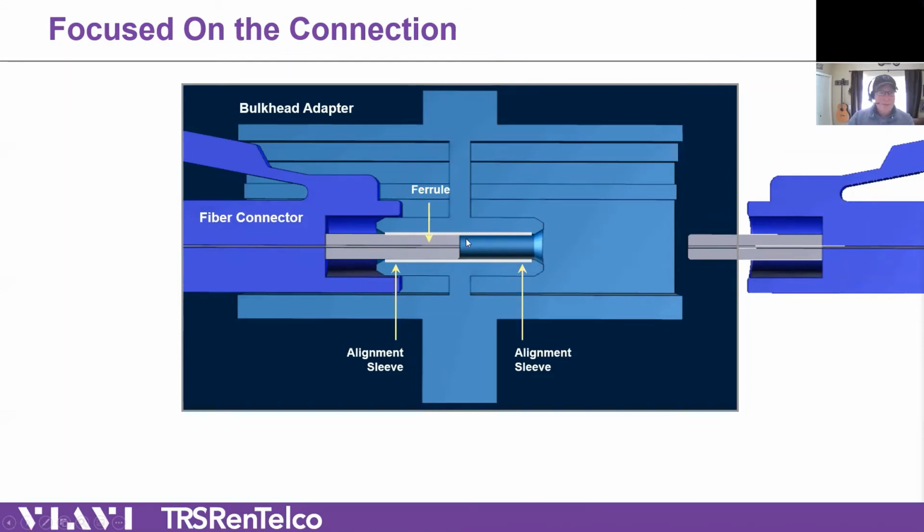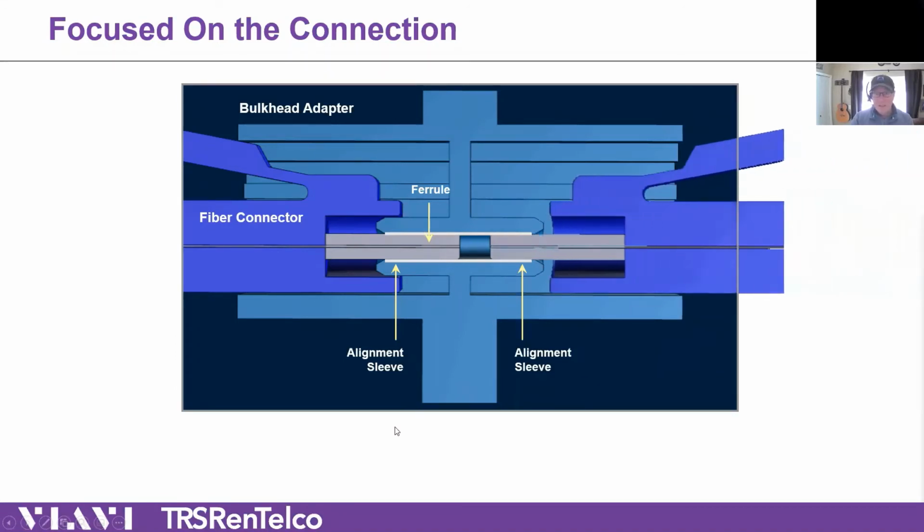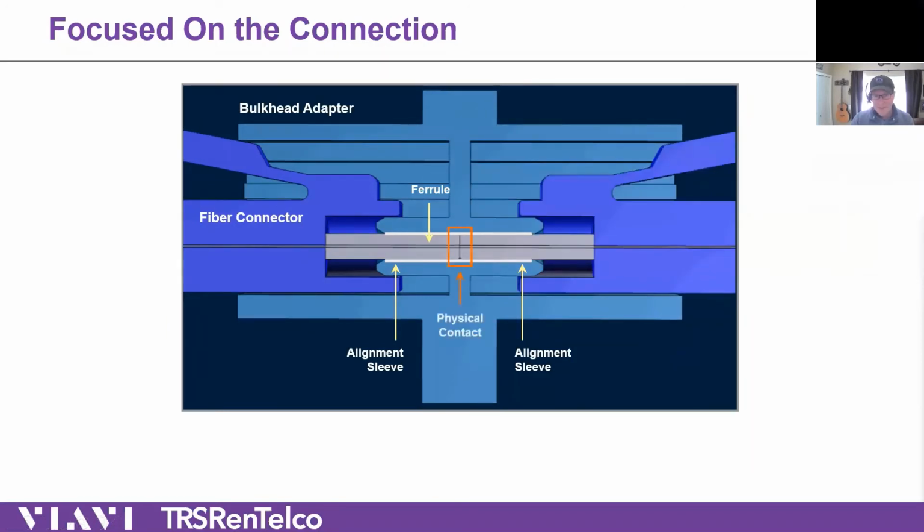And so what happens is when you plug in your connector, no matter which type of fiber, there's a backstop here in blue on the screen that pushes the protection of the core backwards, allows the fiber and the cladding to be exposed, also some of the plastic on both ends, and then this sleeve is just an alignment sleeve, and they connect together. So what does that look like? Looks like that. Seems simple.